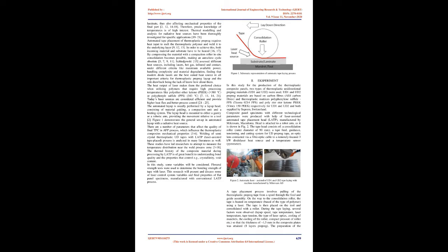7, 8. During the manufacturing process, the laminate is subjected to several heating and cooling cycles which result in residual stresses inside the final laminate. Heat input by means of radiative heating offers advantages for these processes and is well established in different forms. Heating and cooling are affected by many parameters such as layup speed, laser power temperature, layup sequences, ambient temperature, etc. A laser-assisted tape placement system is equipped with sensors to measure the temperature and pressure profiles, improving the bond interface in the nip point region.